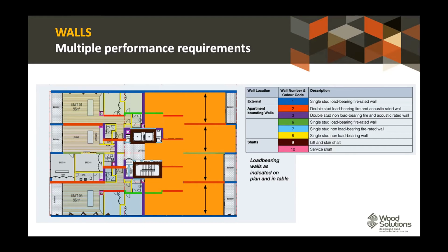But anyway, the first step in assigning the walls through a plan like this is to say, well, where are the boundaries between individual living units, between individual single occupancy units? Because we know that they are going to have both a fire performance requirement and an acoustic performance requirement. And in some cases, if they separate a wet room or a room with a tap from another space, they're mandated to be separated skins of wall.